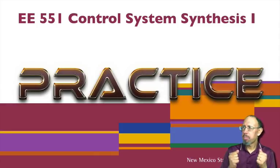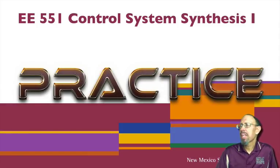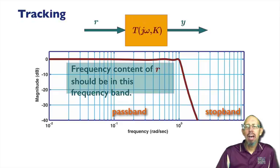All right, let's look at some practice problems. In this case, we have tracking that we're trying to accomplish. And so, again, if you have a reference signal and a closed loop system that involves a controller K and some output Y, basically the frequency content of R should be in some low frequency range. We would call that the pass band.